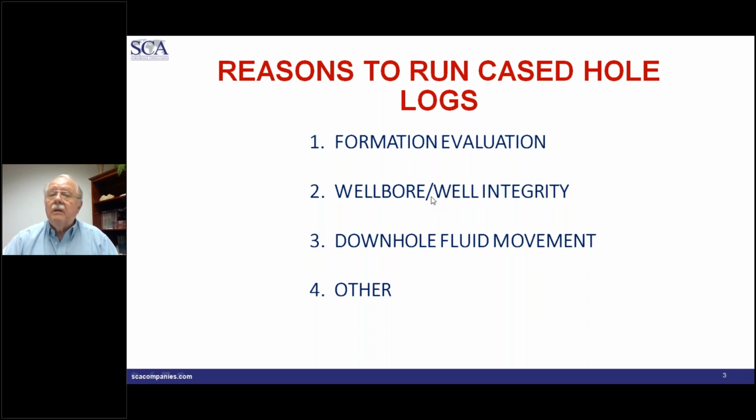Well integrity is a little more than merely the cement quality, though. Oftentimes when you look at the production profile in a well, sometimes things are happening in places that you don't expect. Well, we also have well integrity services. These include the various mechanical services, multi-fingered calipers and like that, and also a number of electromagnetic tools to evaluate the quality of the casing, the wall thickness, and so forth.